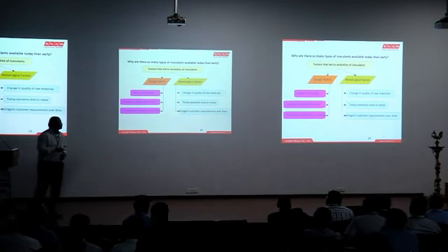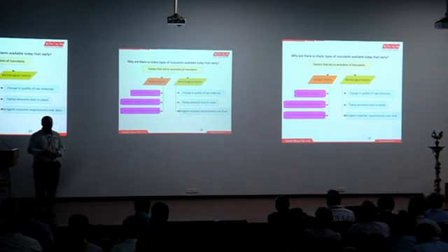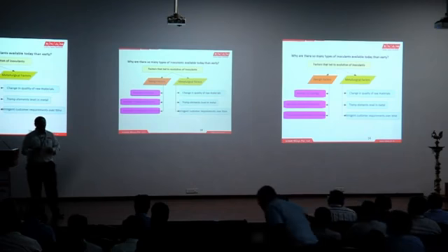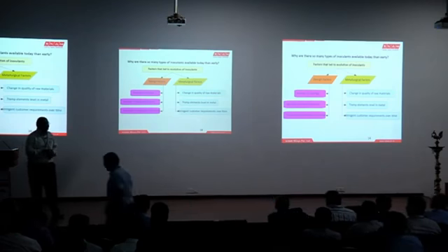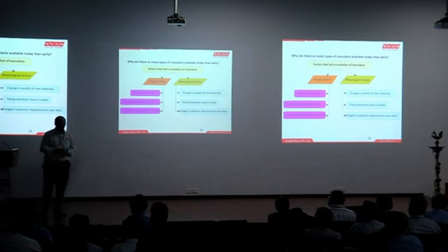Tramp elements level. Maybe 10-15 years ago there was no niobium in steel. Today Tata and Jindal are talking of niobium in steel because they want to do something innovative. They've added the element niobium. So today if we are purchasing some scrap from Jindal or Tata, it will definitely have some niobium. Or mild steel: what we talk of today and what mild steel was 10 or 15 years back is completely different, because every industry is evolving by itself. So the tramp elements level in the liquid metal, introduced through the raw material, keeps varying continuously. But our customer's target is zero defect.